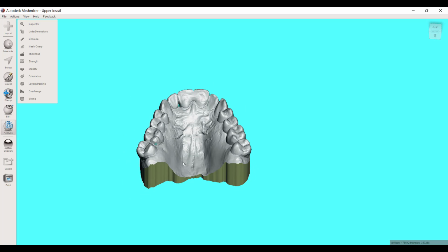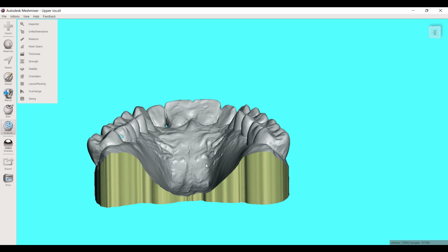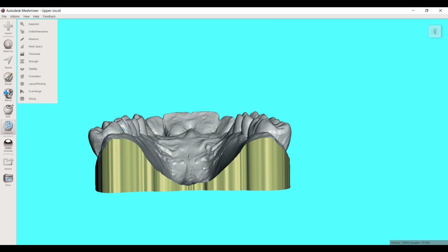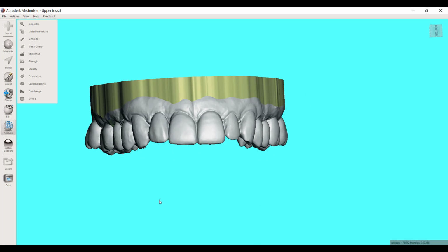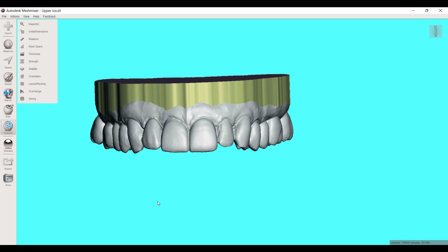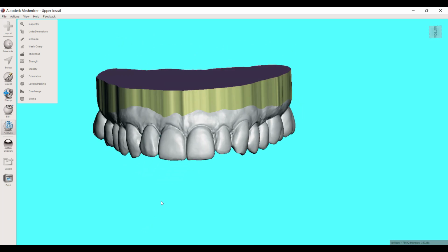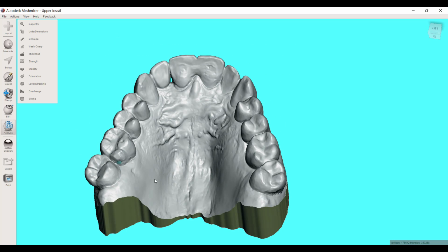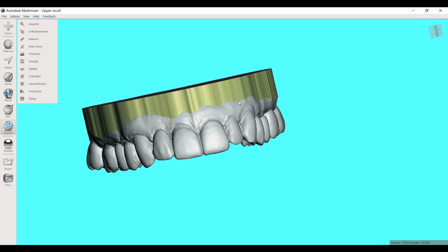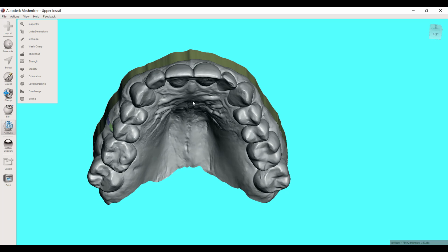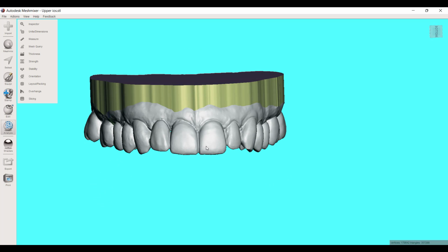All right. Now the only other thing I would suggest you might want to learn just for printing basic models like this is that this model is going to eat up a lot of resin. I would ballpark this to be probably 30 or 40 milliliters of resin, which is really unnecessary. We don't need this to be a completely solid model. So one of the things that will save a bunch of resin for you is actually hollowing this model. All right, so let's go to Edit, Hollow,